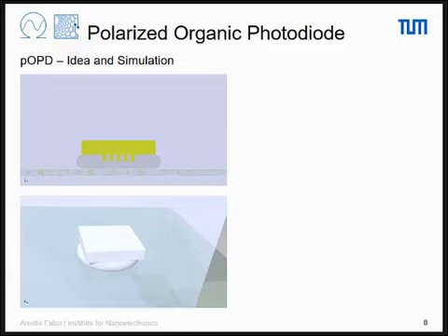So we maybe pay 10,000 euros to get an E-beam stamp at the nanoscale, then we do not need to pay money anymore. We just do it almost for free. Once you remove the stamp, you have a negative replica, which in our case is okay, since it's grid lines, so negative and positive are almost the same. We just need to evaporate aluminum. If you evaporate aluminum now, you will have an aluminum layer on top and an aluminum layer in the grooves, which is exactly our bilayer grid polarizer. That's why it's very easy, and it's better than a single layer grid polarizer. At this point, we have an aluminum layer that we could use as an electrode.